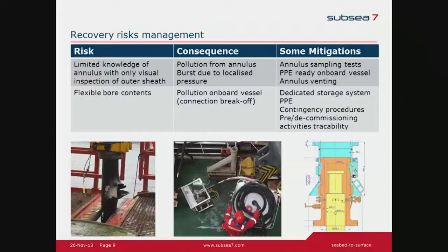Flexible bore content: if we recover a pipe, we need to know what is inside, in case we need to break off the subsea connection and will be exposed to the content. The consequence could be pollution on board the vessel, and how to manage it. So we need equipment to store the contents, the right PPE, contingency procedures in place, and good knowledge of the decommissioning performed before.